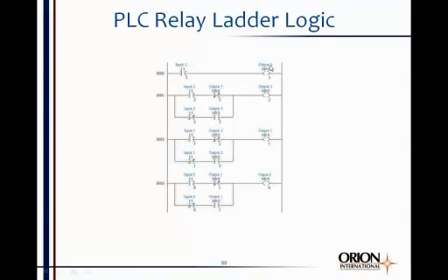These outputs are represented as coils, and coils can have auxiliary contacts associated with them, but there's some kind of a real device associated with that output. It may be a light or a motor starter. You don't know what the outputs are unless you get into the program and determine that. But they consist of these input contacts and output coils, and there are also auxiliary contacts associated with the output coils, just like a real relay.